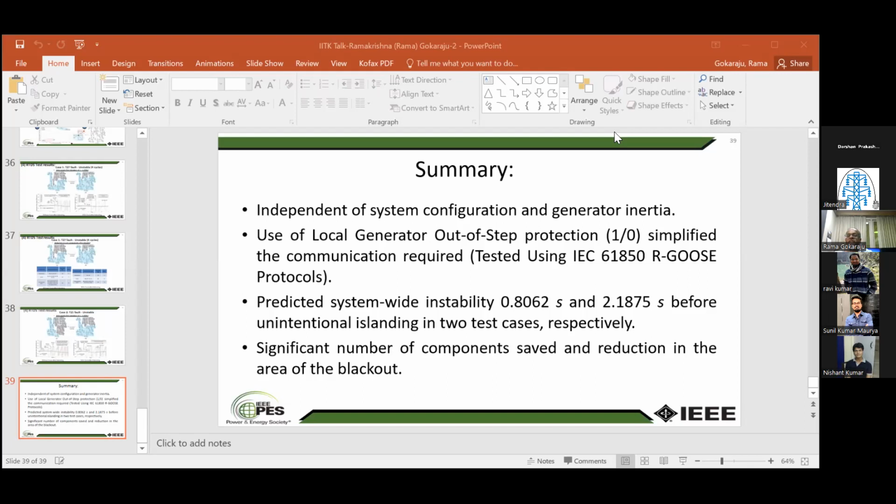So what will be the effect of correction measure on the system operation during a false prediction? It can happen for a boundary condition. As long as it is a marginally stable case, like the earlier question Ravi asked, say the acceleration and deceleration areas at 180 minus delta, around 150 degrees.